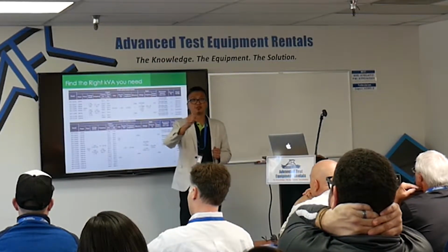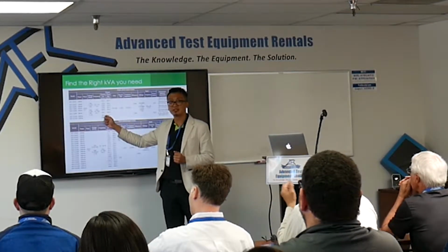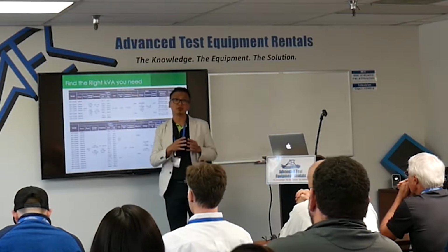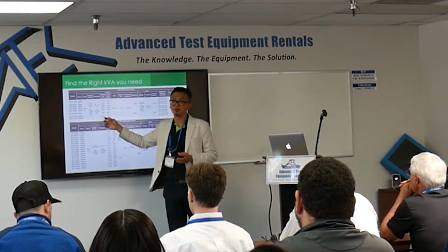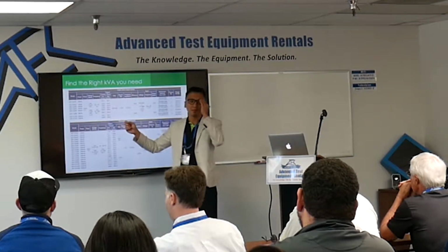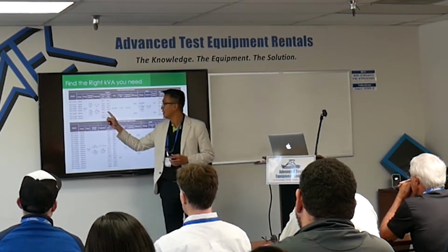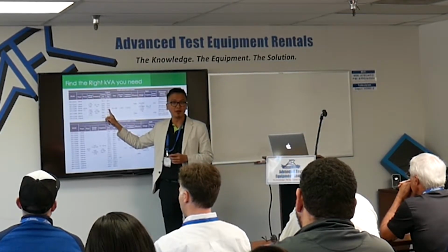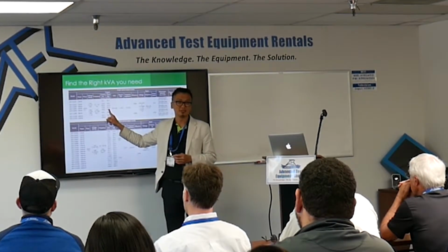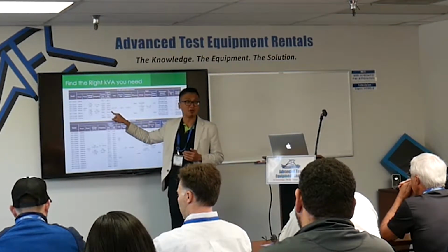You can switch the voltage range on the power supply. In the low range, you can pull out more current. In the high range, you may support higher voltage but lower current. So you have to check whether your test unit is above the maximum current value or not. If it's higher than that current, you have to jump to the other range, okay?